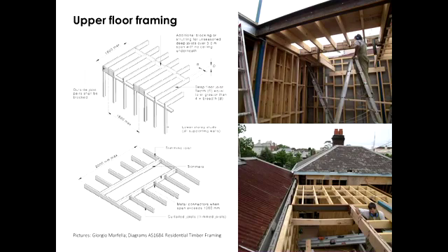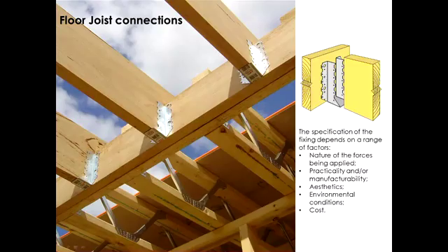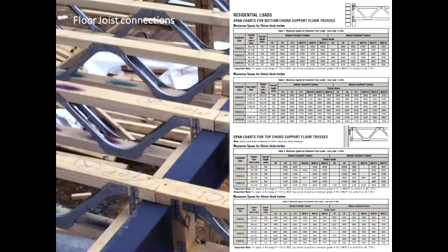Upper floor framing. Well, we've already seen the joists up there. I don't think you're going to use those joists in your case study. In case you need to open a skylight or you have stairs, then you need those trimmers that restore the discontinuity you've generated by cutting the joist. This is a typical floor joist connection with galvanized plate. And the posi struts.